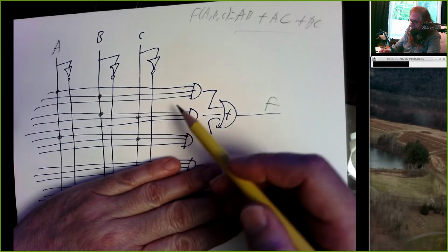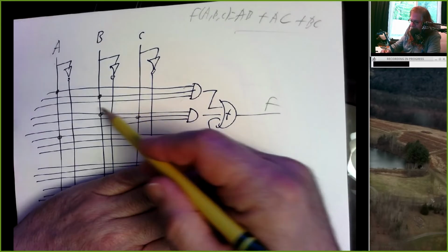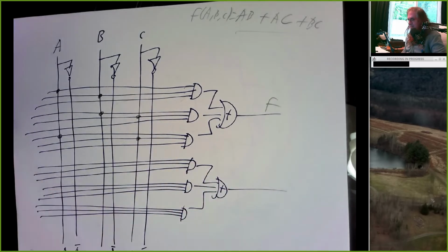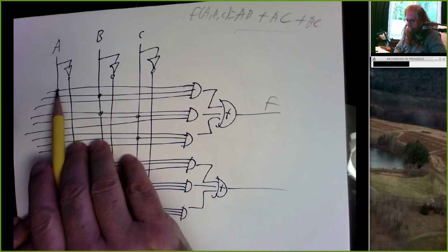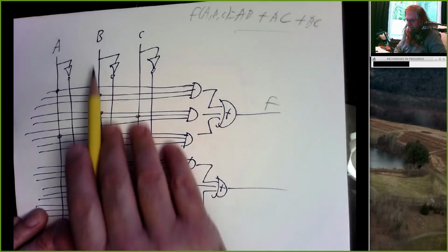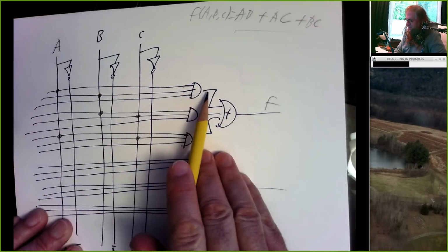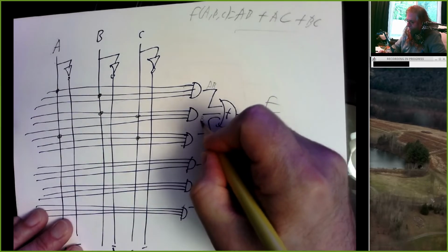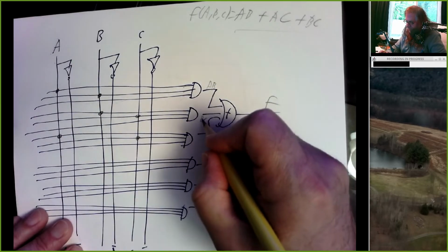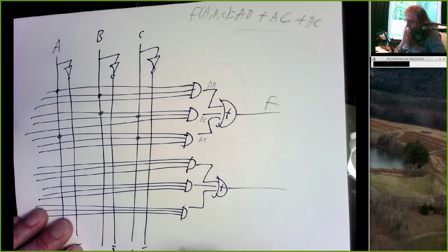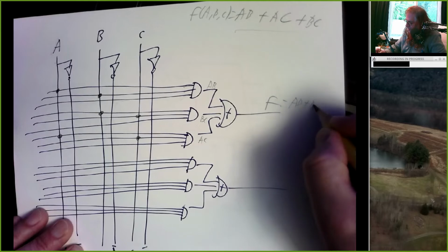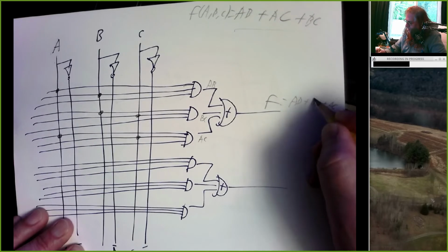And maybe I'd get an eraser. I'd erase this line over here that's not connected to anything, and I'd erase this line that's not connected to anything. But functionally, what am I doing? I'm taking input A, putting it into an AND gate, taking B, putting it into an AND gate. This output right here is AB. This output here is BC. This output, sorry, yeah, BC. This output is AC. And this is the OR of them. So it's AB or BC or AC.